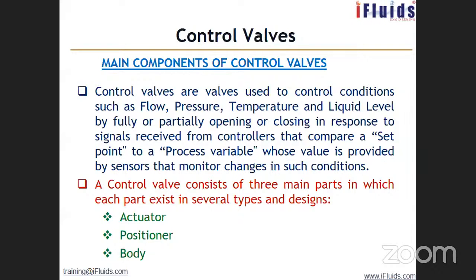And we always have a set point. Suppose you want to maintain the pressure at, let us say, 25 bar, that is called the set point. It can vary between 20 to 30, etc. Plus or minus some variation is possible. In any given process, you cannot fix a particular variable at one value, because it is a dynamic environment.